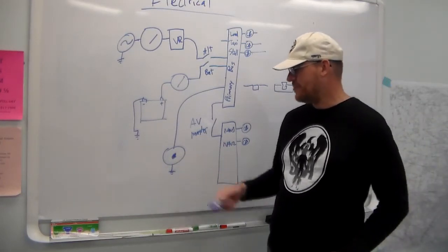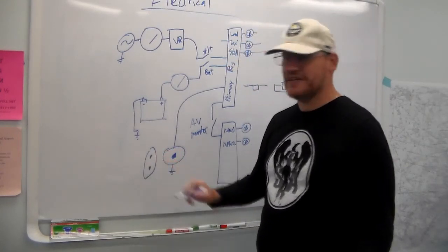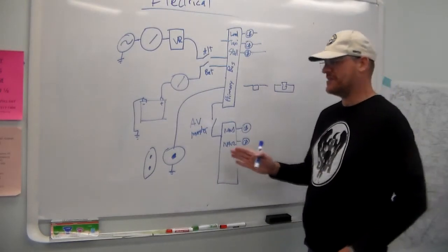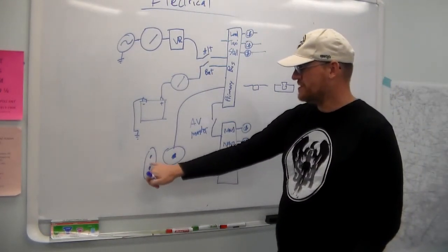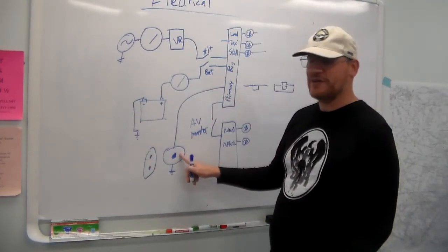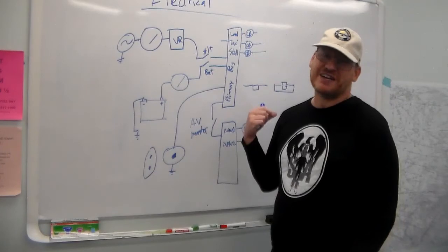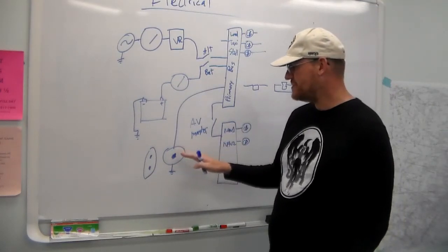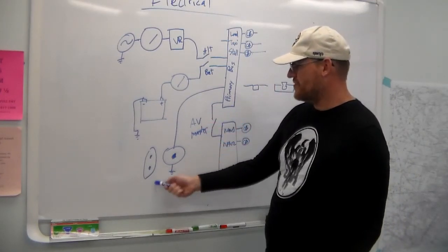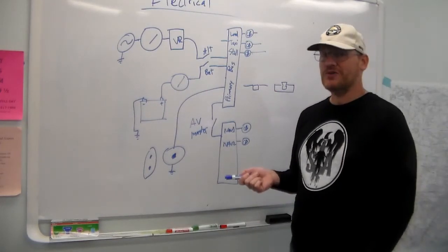So you might have a plug that looks like this, or you might have a plug that looks more like this if you're flying in a Cessna. These are in different places. Some of the Cessnas, they have these up close to the front, up by the meat chopper. A lot of the Pipers are a little bit further back. The Alaris actually had a Piper style plug way back at the tail. So, different options for these. So these can be used to start your engine if your battery is too low.